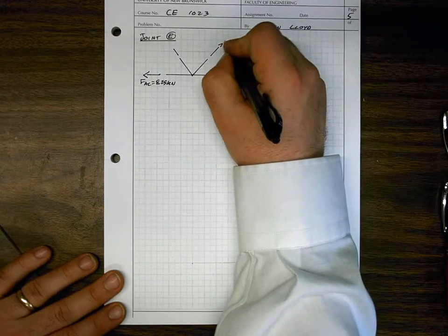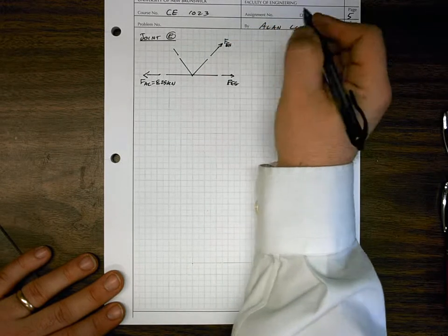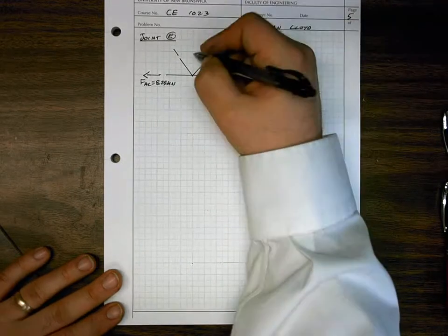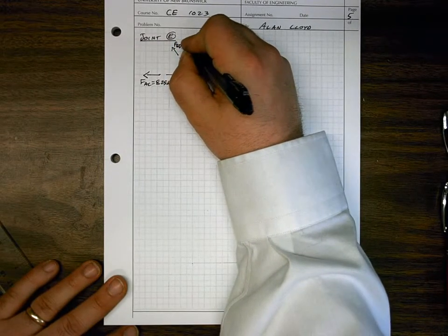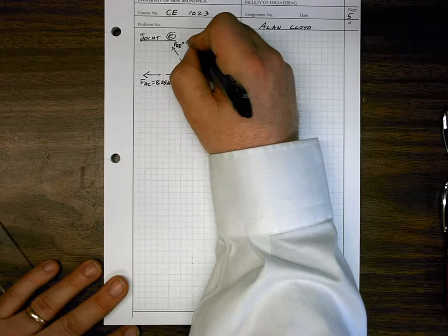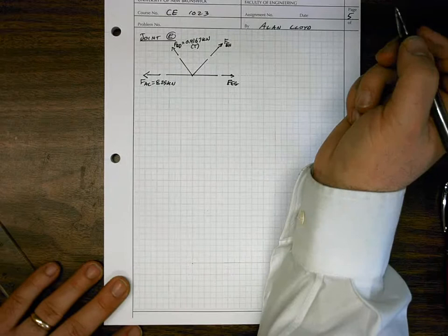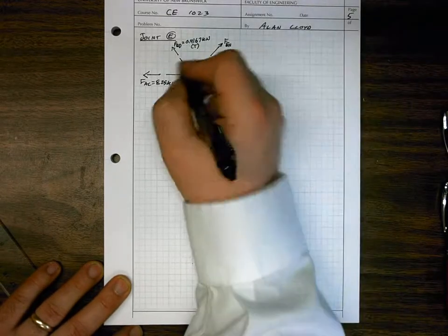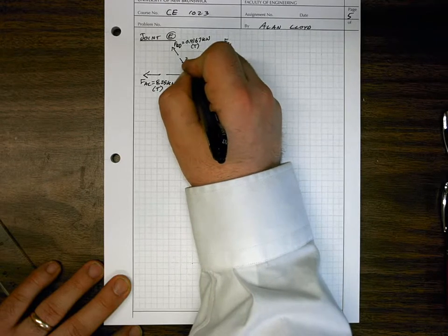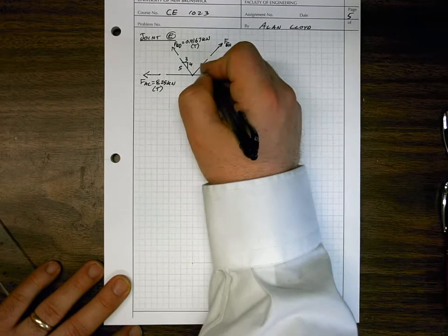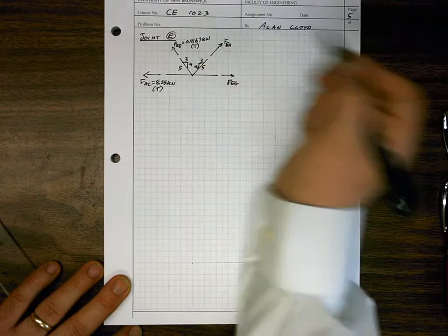We have FEH, that's also an unknown, so we're going to draw it going tension positive. We have FED is equal to 0.4167 kilonewtons in tension. We drew it as in tension because that's what we calculated before. We know some stuff here. We've got a 3, 4, 5 triangle. You see that all over the place here in this problem. On both of those chords we have that.